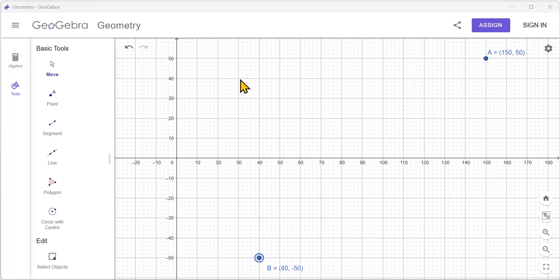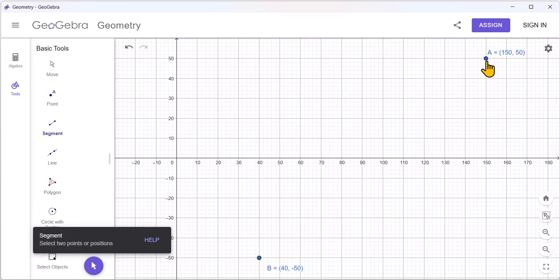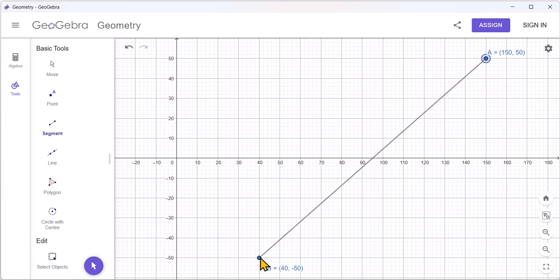Okay, I might as well continue with actually constructing this example. So in this example, we have 150 for sigma x and 50 clockwise shear stress. And for sigma y, I have 40 and obviously minus 50 for the shear stress. So this would be my 2 points. I connect them as we discussed in the previous example.